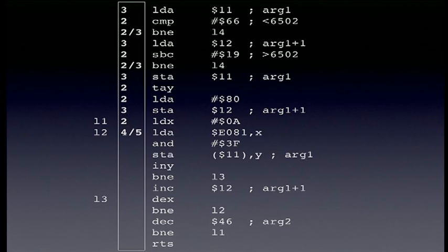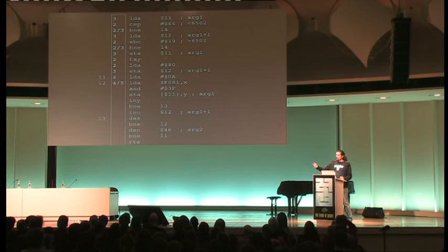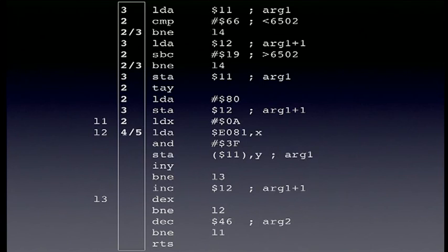Then this one is interesting. The load, the operand 1, operand 2, that's 3 fetches already. Then the actual fetch from memory, so that's 4. But in case we have an overflow, in case we have a carry into the next page in here, then the ALU has to do 1 extra step, so that's 5 cycles.